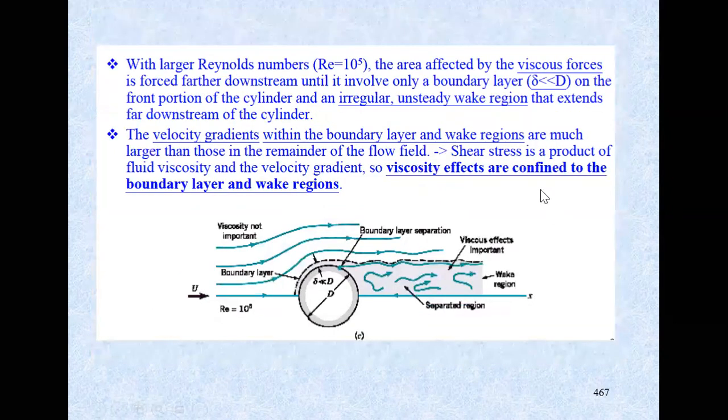As the Reynolds number goes higher, the separation becomes even earlier. Then you have a much bigger wake region, and you're going to see different flow characteristics in front and behind that will also influence the drag.